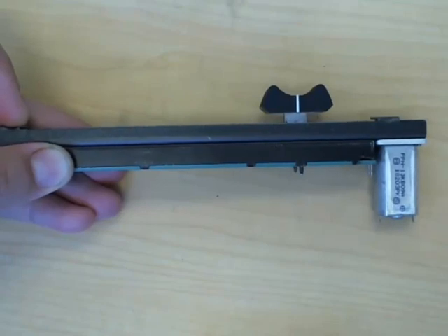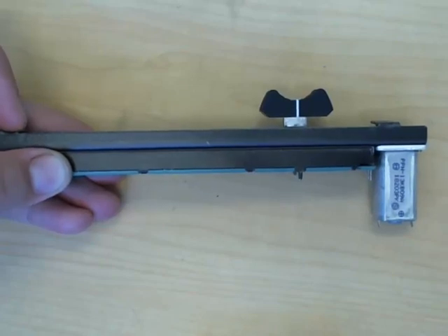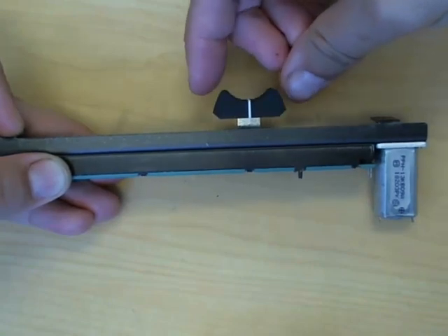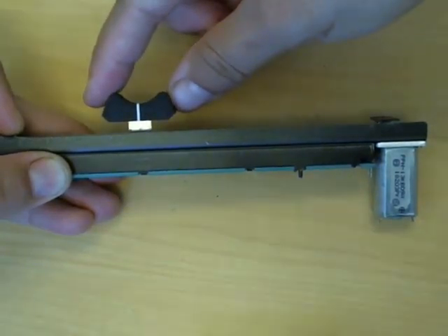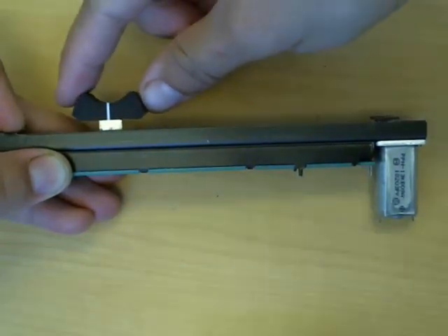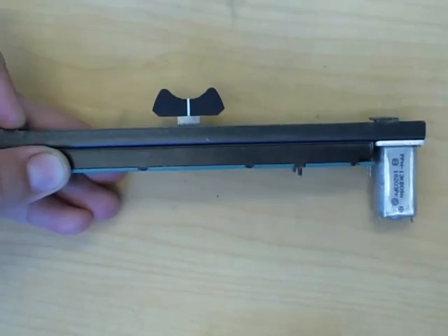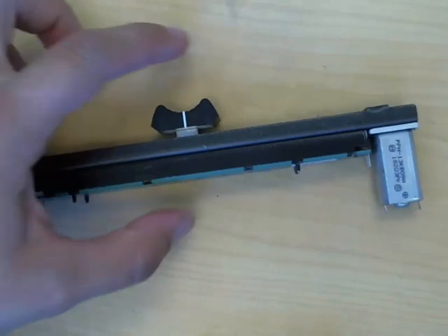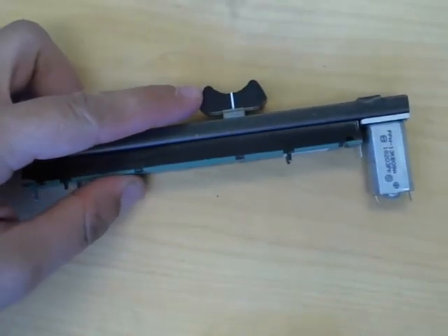When I've completed my calculations from inverse kinematics to calculate the location of the end effector, what I get out is the value for these joint variables. I have a value for D telling me where I want this slider to be in order to get my end effector to its desired position. So I want to be able to control not the velocity of this slider, I want to be able to control its position.